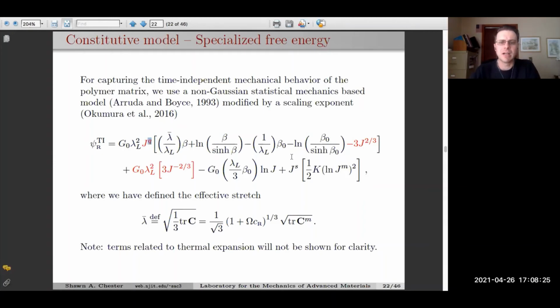And so you'll see here this very last term, that's where we add on our bulk modulus, so it's not 100% incompressible. Right? So the log Jm is just the mechanical portion. And the Js is floating out front because this is an energy per reference volume. However, this term right here inside the square brackets would be after already swollen. Right?